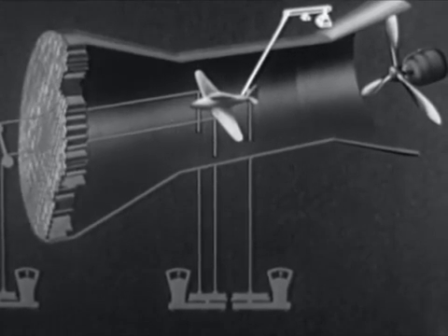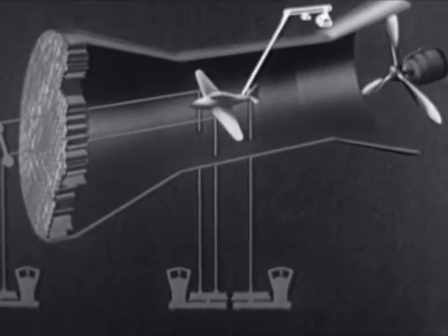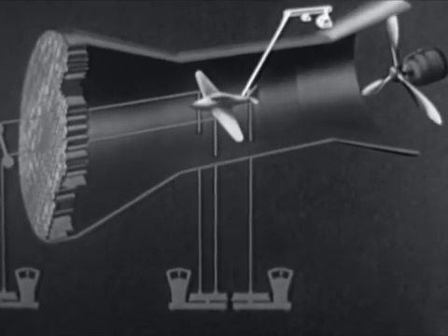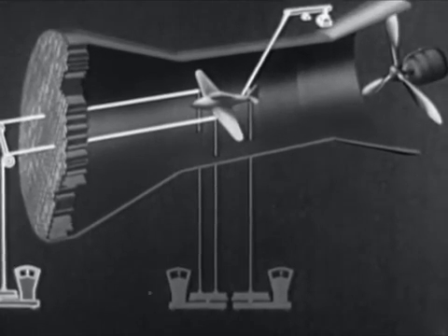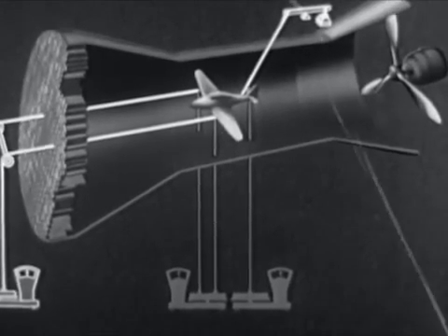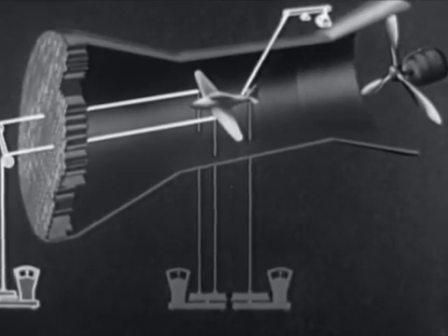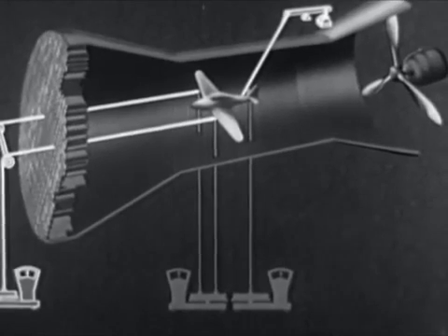One wire runs from the model through the top of the tunnel to a balance arm which is weighted so as to maintain tension and compensate for other forces. From the leading edge of each wing, a wire runs forward in the direction of flight, over pulleys, and down to a bar on a platform type of scale.